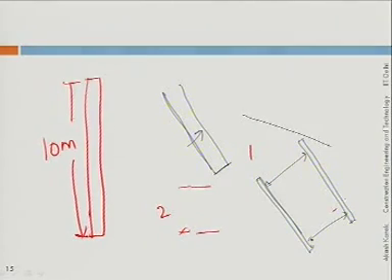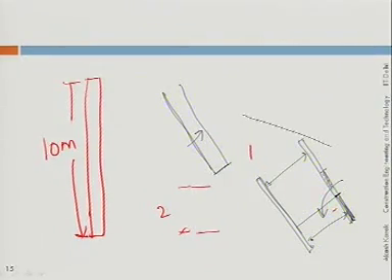But not in one go. What you do is first you put the top shutter only up to here. You pour the concrete up to here. Then you bring another shutter and you put it here. Then you concrete it here. Like this you do.